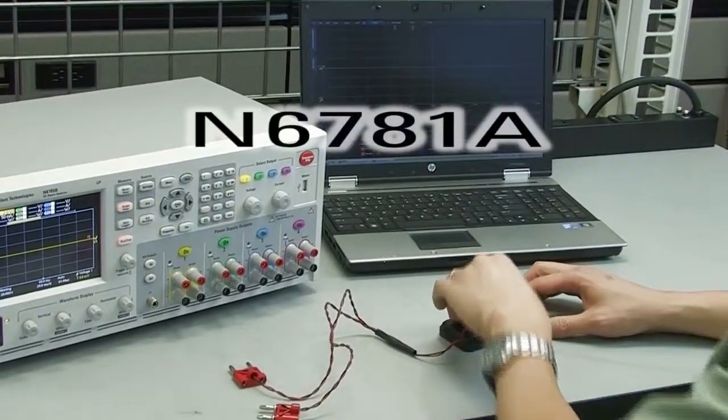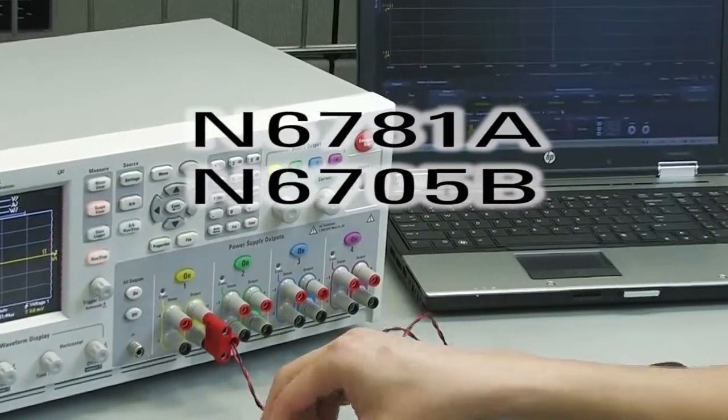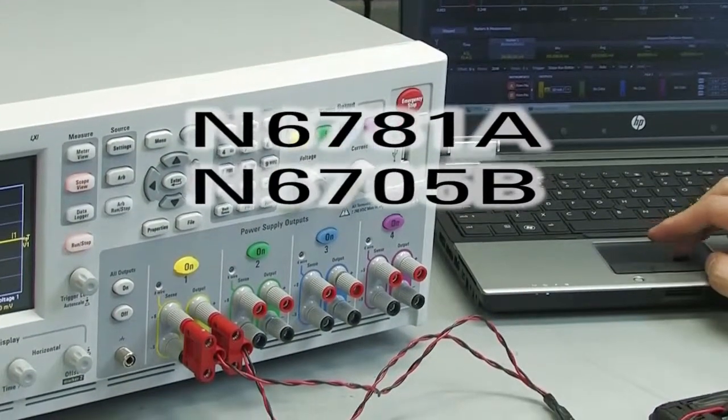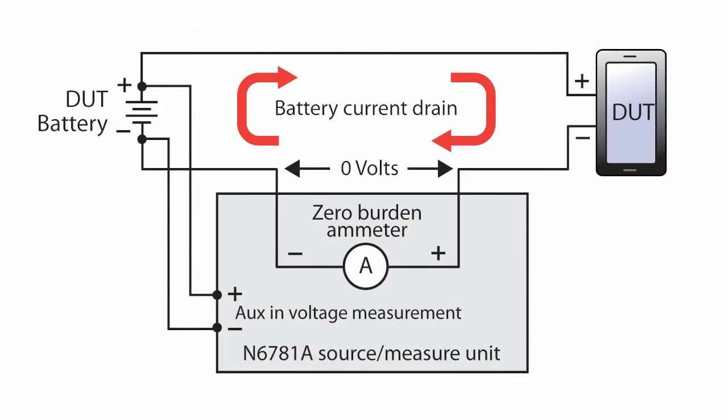The N6781A and the N6705B mainframe have a number of unique features and advantages that provide improved accuracy and greater insights, specifically when you conduct a battery rundown test. It offers an independent DVM input for logging the battery voltage, and it is a true zero-burden shunt, eliminating the voltage drop problem of conventional shunts.